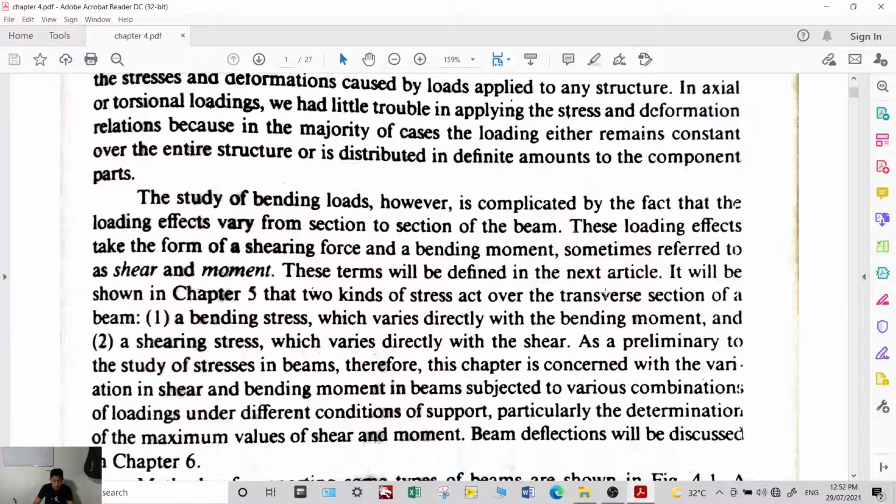So, in a beam, every section experiences or handles different shear stresses. So it is important that we are able to determine the maximum bending moment and maximum shear force that we will use in our design, so we can know the maximum load that the beam is carrying. Okay?